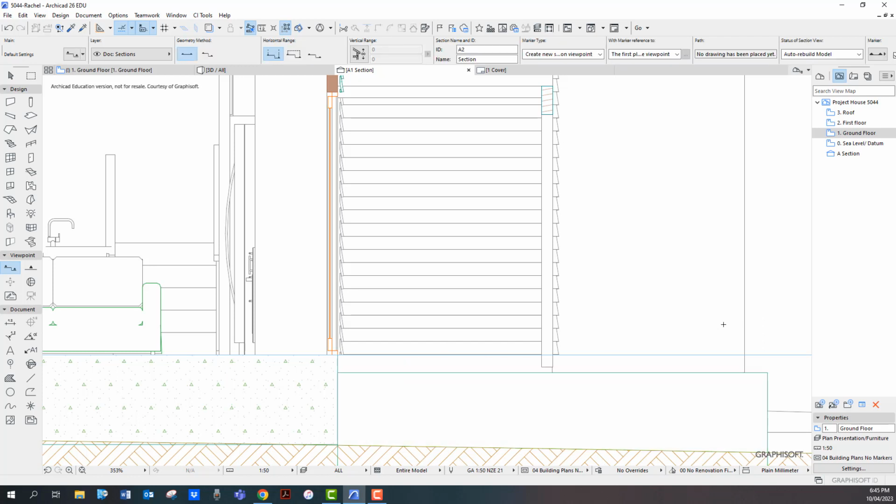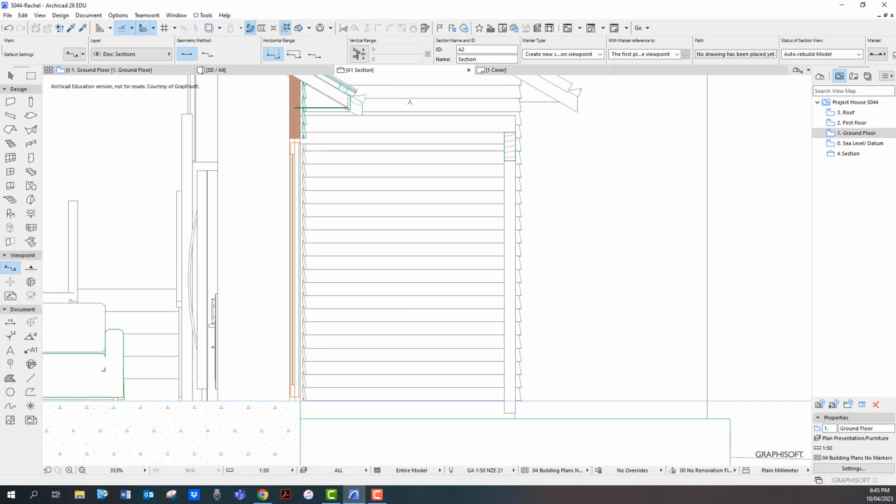And once you've got your deck level established and the finished floor level here, our column is probably a little bit small here now. So what I'll do is I'll just measure. I'll just leave this beam the way it is at 240. I'll go up to the measuring tool, or I'll press M, and I'll just say, well, from that column to here, it's going to be 2160. So you can just about see that. So I know when I model my columns, 2160, but even if you don't get them right the first time, we can always adjust it in section and before we drag any copies. So let's just try that.